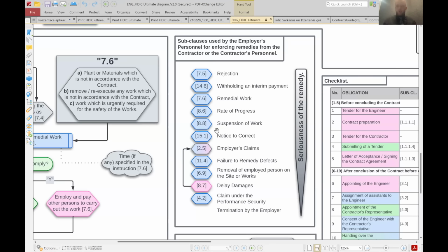Just to give an example, there will be a delay cost. Sure, there will. When you're suspending the work, the contractor cannot work. There will be a delay cost, and the contractor is actually able to claim that, but he's not able to claim it if the suspension was because of his mistakes. But again, it's a procedure where you can expect arguments to happen. You can expect some emotion on your construction project, and it's normal. It's usual, and sometimes it is really necessary.